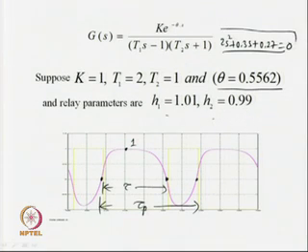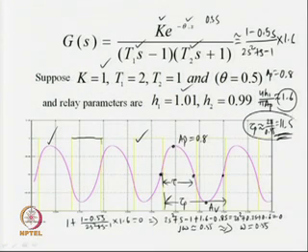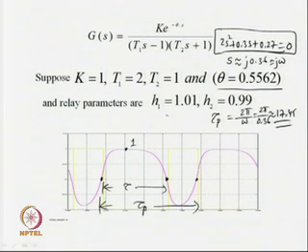Now, what do we get from this characteristic equation? It gives us the location of the poles, or the values of s. Now, s will be roughly equal to j0.36. This is also equal to jω, which implies that the period τp will be 2π/ω = 2π/0.36, which is roughly 17.45. As expected, τp has increased. Earlier it was roughly 11.5, and that has gone up to 17.45. So, this is how the time period of the stable limit cycle output signal increases with the increase of the time delay term.